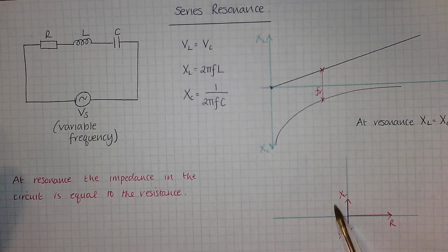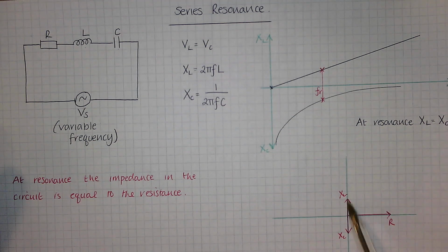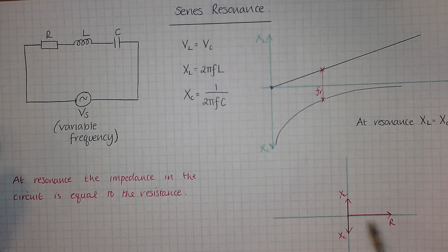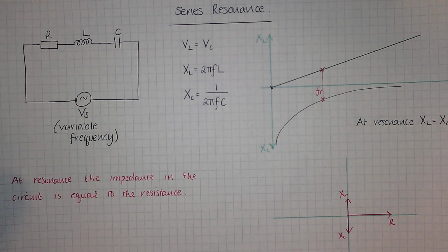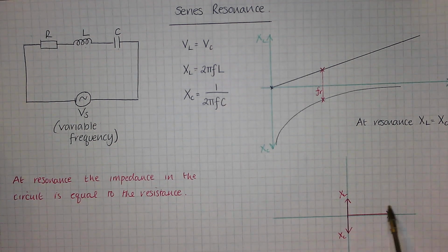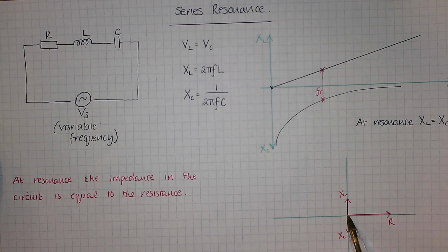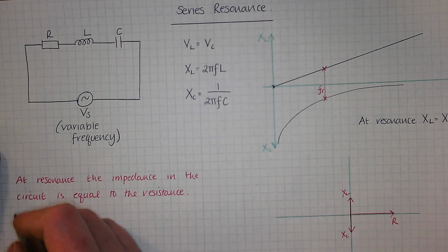And in terms of the impedance in this circuit, because these are equal and opposite, you can't have any more. That's the lowest value of resistance or impedance you could have in this circuit. If you added in a bit of XL, you would increase that and you'd get a hypotenuse, which would be larger. So that is the circuit at its minimum value of impedance.